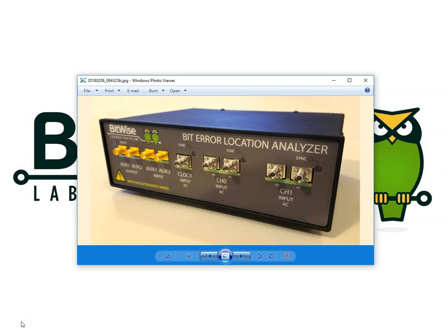In addition, exact bit error locations can be organized into symbols, and symbols organized into blocks, and blocks can be interleaved, allowing you to see symbol error statistics on block boundaries. This type of analysis is key to understanding correction strengths needed by forward error correctors to achieve error-free performance on some of the channels used today. There are many techniques for studying error location, which we'll get to later. For now, just imagine how much more diagnostic it can be to know if all your errors came in, say, groups of 3 separated by some perfect interval, and how much more diagnostic that would be over just knowing the count of how many errors happened.